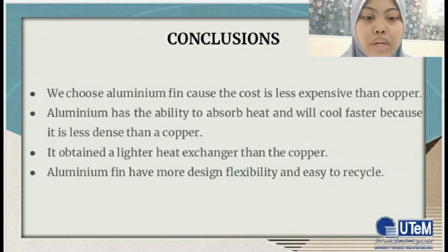Alright, I will explain the conclusion for our task. We chose the aluminium fin because the cost is less expensive than copper. Besides, aluminium has the ability to absorb heat more and it will cool faster because it is less dense than copper. It also gives a lighter heat exchanger than copper. Lastly, aluminium fins have more design flexibility and are easy to recycle. So, aluminium is the best choice for our product.